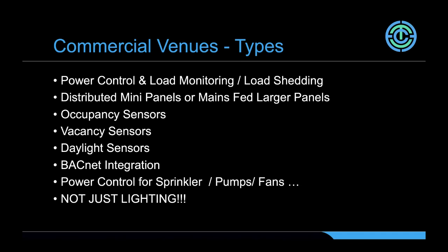Our commercial venues need more than just the power controls. They have to have the ability to interface with our occupancy sensors or even third-party occupancy sensors, vacancy sensors, which operate in a different set of criteria, daylight sensors and daylight harvesting, or ambient light monitoring for a physical space. We have a variety of sensors in all of those 3 classes that are either wall or surface or through beam or remoted or exterior. We have sensors pretty much for every size and flavor that are required.